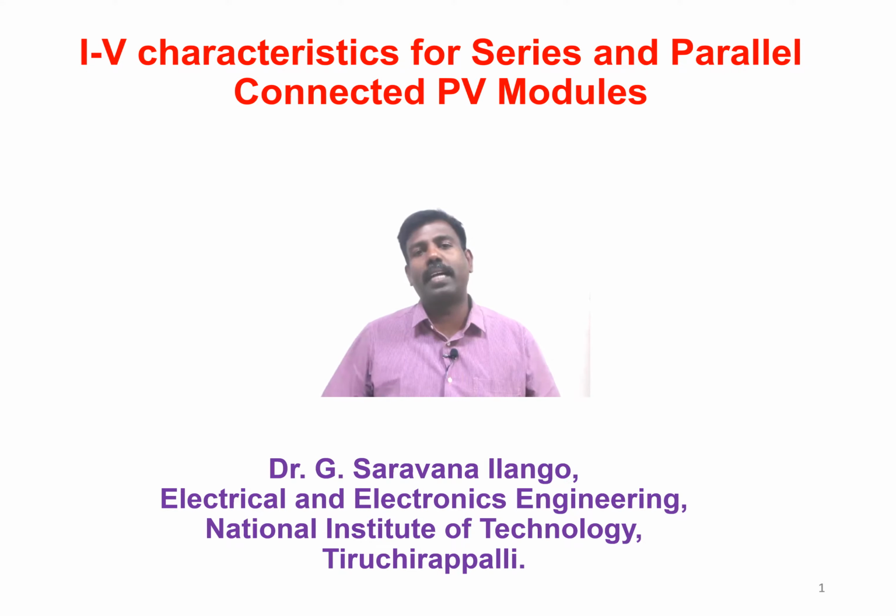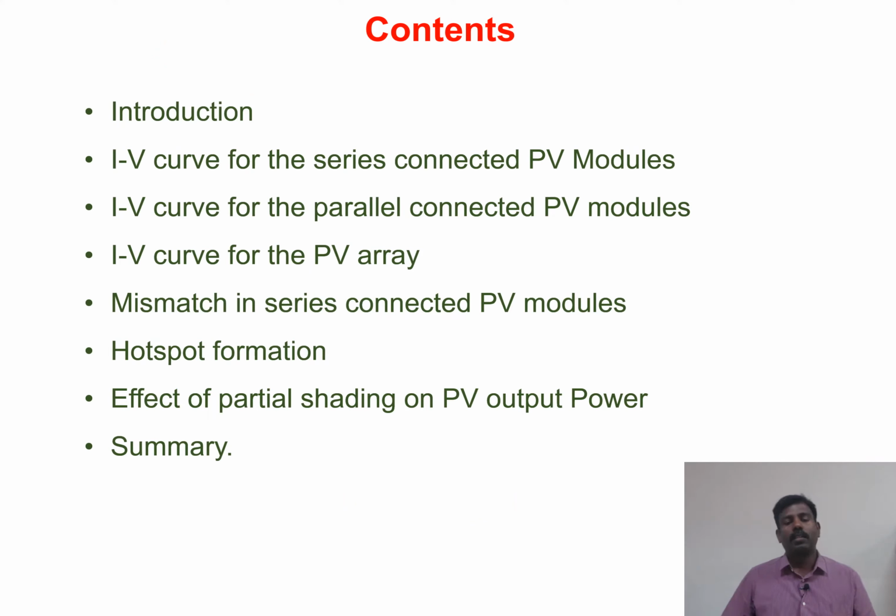So in that case, to match the load, PV modules are connected in series and parallel to match the loading condition. In this lecture, we will see how the IV characteristics look if these modules are connected in series and parallel. And this is the overview of my presentation.